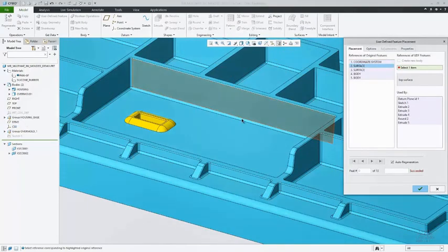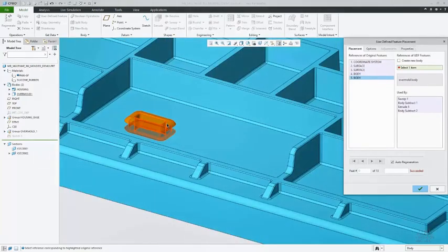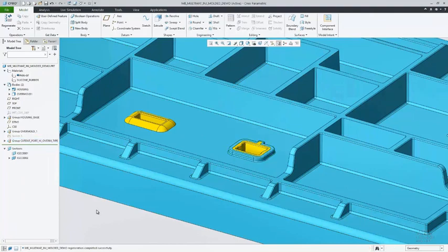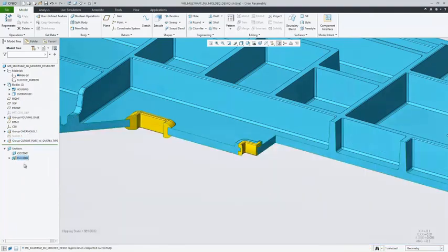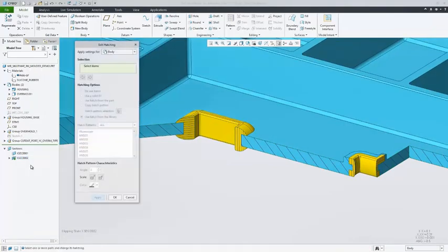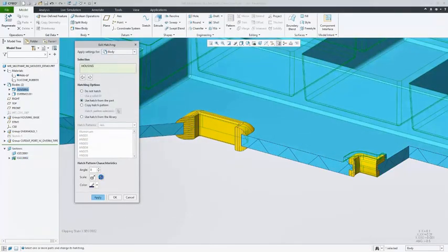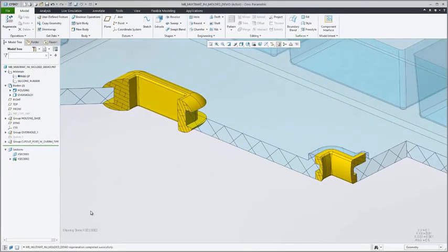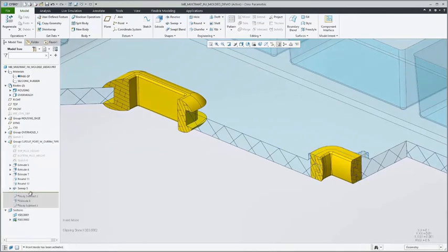Reuse design intent and body definitions captured in user-defined features. When you place a UDF with the advanced reference configuration workflow, you can map each body reference to an existing body in the model or create a new body on the fly. You can use cross sections and define hatching per body, and if a body material definition includes the reference to a cross-hatching pattern definition, then you can choose use hatch from the part to apply the hatch pattern according to the material of the body.